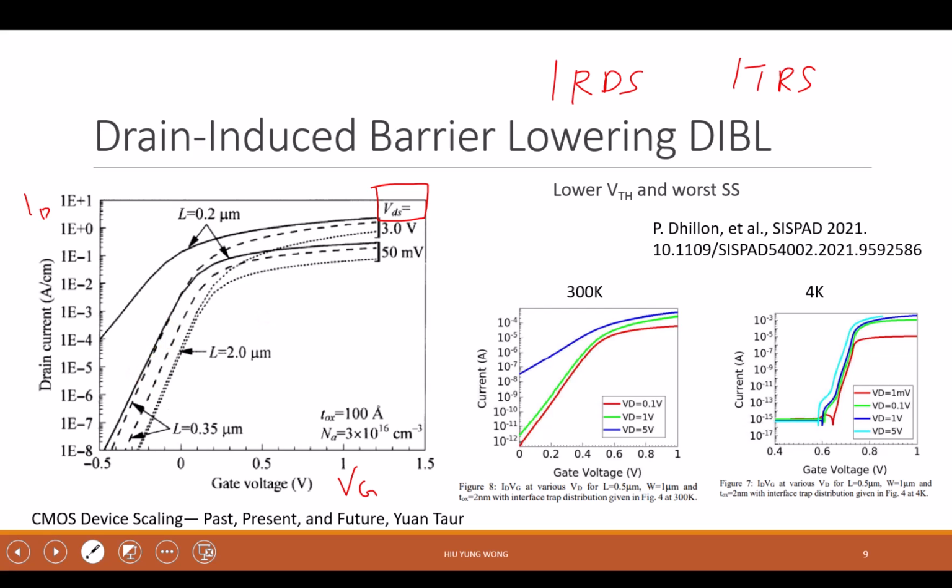But when you compare papers from different companies, if you care about VTH, then you look carefully at which VTH they are talking about. What is the definition? Okay, good. So just a reminder to everyone, it's good to take a look carefully. This is L equal to 2. Again, old technology, but it's the same. This dash 9 at L equal to, what do you see? When it is at 50 millivolts, it means linear mode. This is linear.